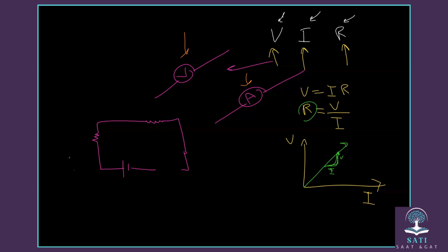Into the circuit. The ammeter is connected in series, so that means you put the ammeter here, and in series means it connects as part of the path of the wire itself. So the ammeter is connected this way. That means if you take this ammeter away, no current will move through the circuit. While the voltmeter, you connect it in parallel.